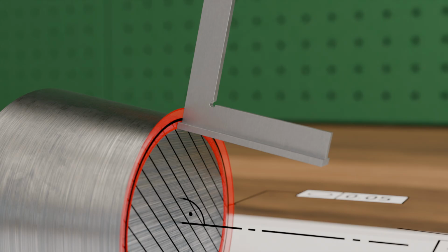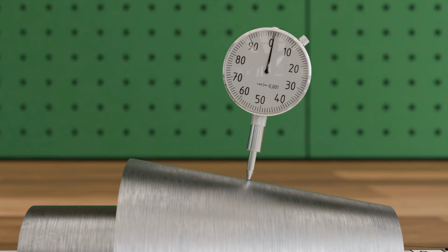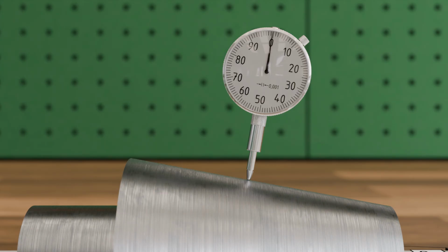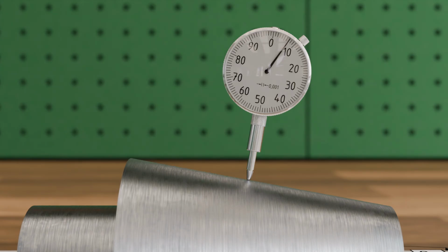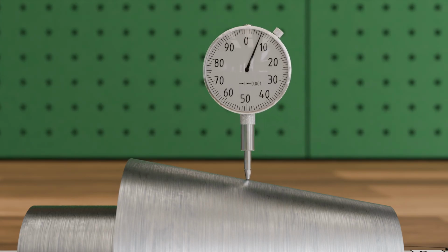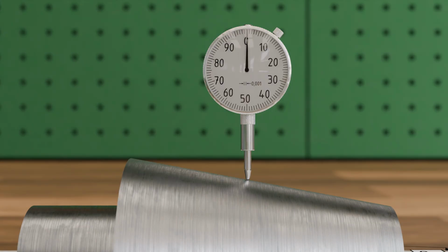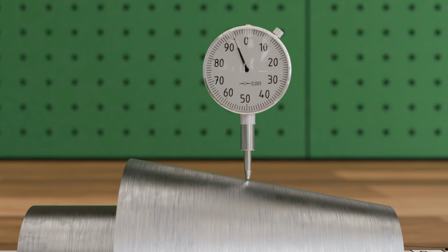This distinction whether roundness is tolerated perpendicular to the axis or perpendicular to the surface must also be considered when measuring roundness with a dial gauge. If roundness is tolerated perpendicular to the surface, the dial gauge must be positioned perpendicular to the surface as well. For a roundness tolerance of, for example, 0.05 mm, the dial gauge's needle may then deviate by a maximum of 0.05 mm. If the roundness is tolerated perpendicular to the axis, then the dial gauge must also be aligned perpendicular to the axis, and the maximum needle deviation in this plane must be observed. The deviations measured perpendicular to the axis are generally different from those measured perpendicular to the surface.